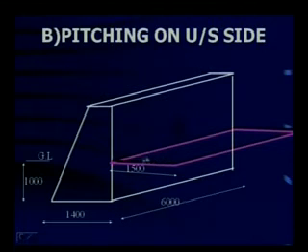And now see here, this is the area where pitching is to be done. Pitching is nothing but laying of stones along this area. Is it okay? Now you need to make an excavation here along the apron on the upstream side. What dimensions do we require? You need the length. The length is same as that of the head wall, that is 6 meters. The width here is 1.5 meters.